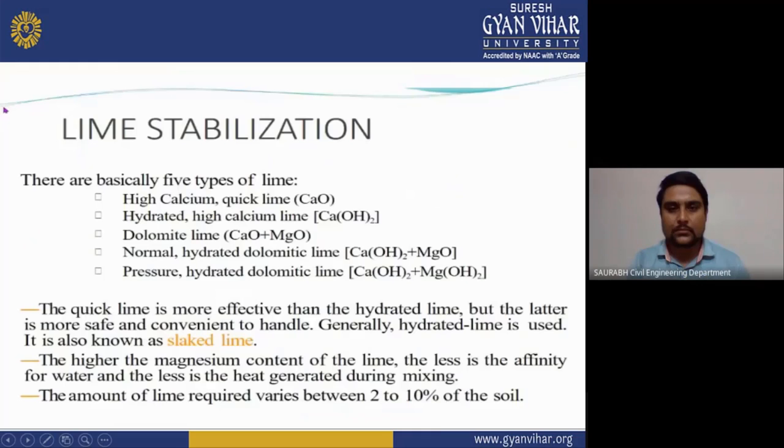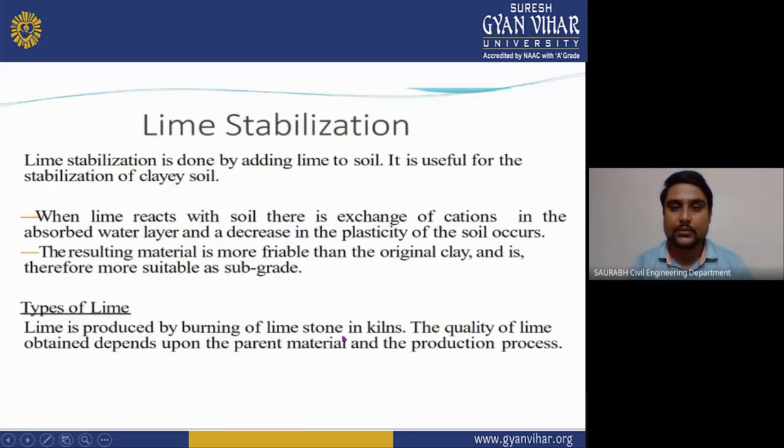Okay, we were on lime stabilization. The higher the magnesium content of the lime, the less is the affinity for water and the less heat is generated during mixing. The amount of lime required varies between 2 to 10% of the soil.